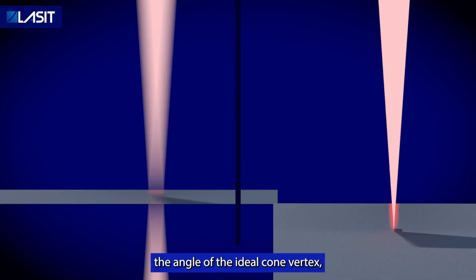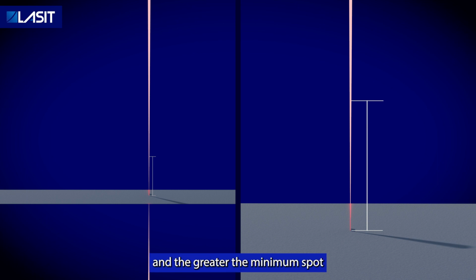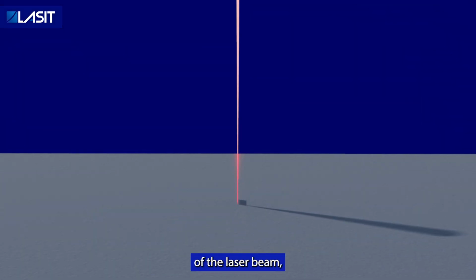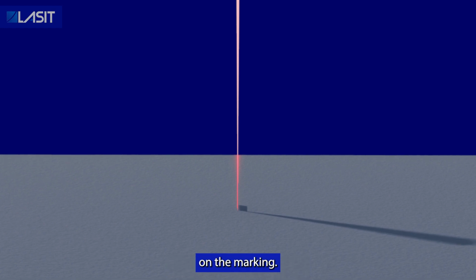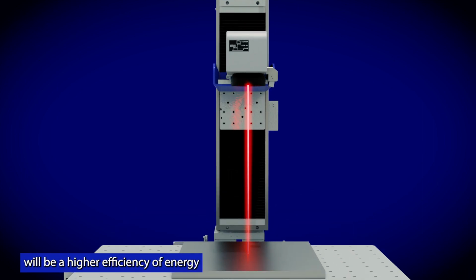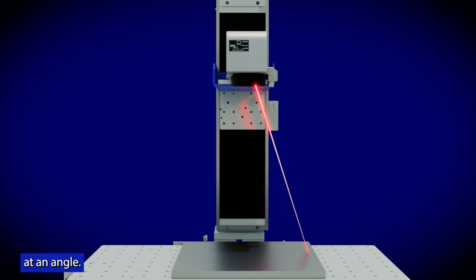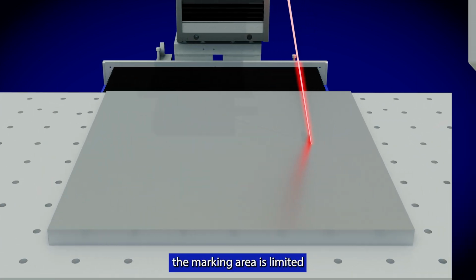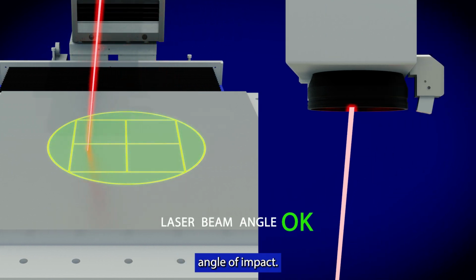The more acute the angle of the ideal cone vertex, the more the tolerance increases, and the greater the minimum spot of the laser beam, producing a different effect on the marking. When the laser beam impacts the material perpendicularly, there will be a higher efficiency of energy transmitted to the material than if it were to impact at an angle. For this reason, the marking area is limited so as to preserve an acceptable angle of impact.